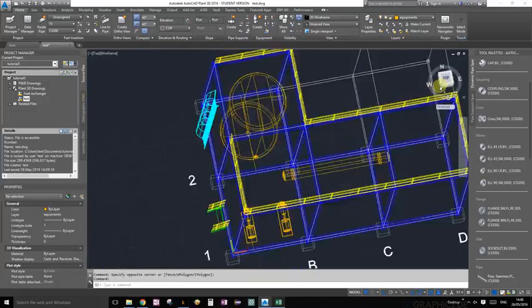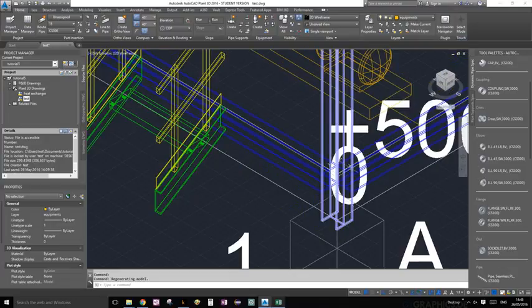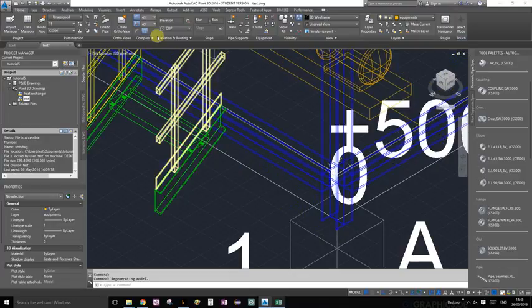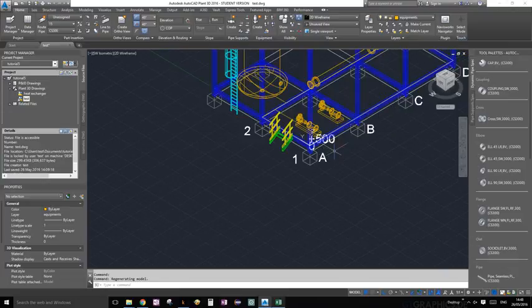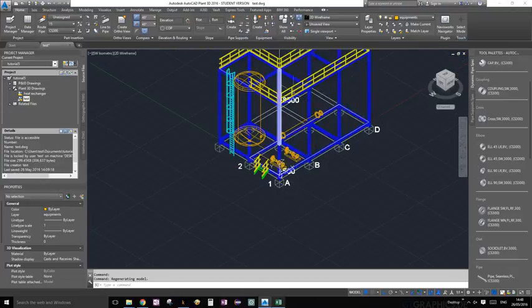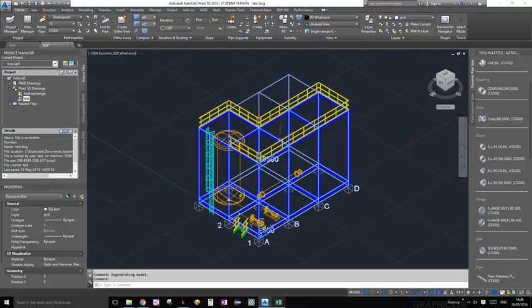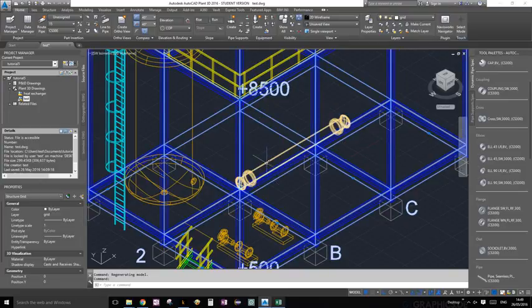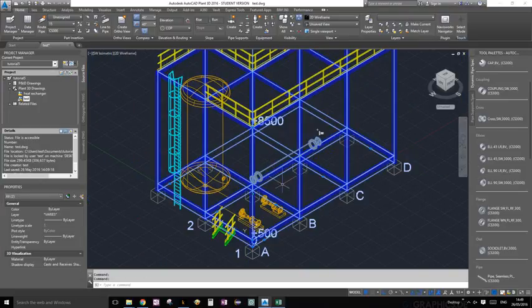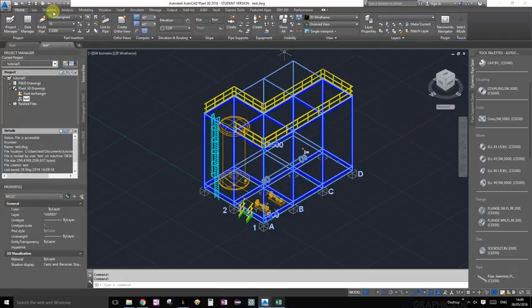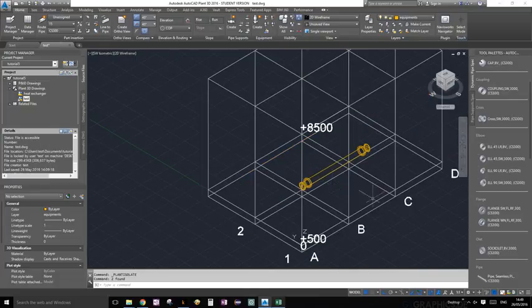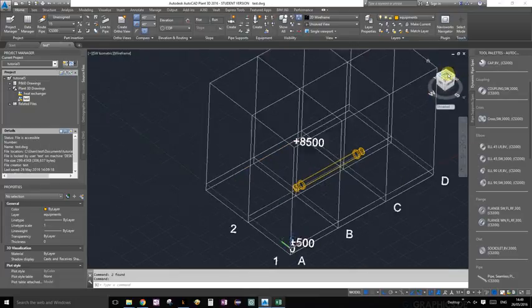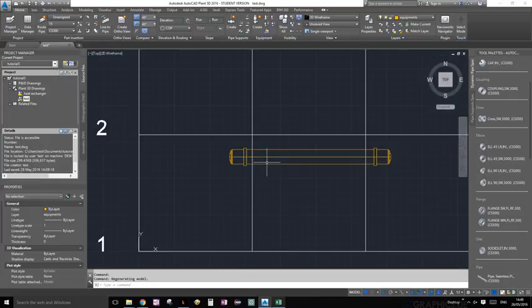Also, another thing I forgot is to make sure that our user defined coordinate system is exactly on top of this first platform. To do that, we should restrict our views first. Let's choose the grid and our heat exchanger and hide everything else. So again, to hide, from the Home ribbon, go to the Visibility palette and click on Hide Others. Perfect. Okay, so let's go back to top view. Perfect, now we can see.